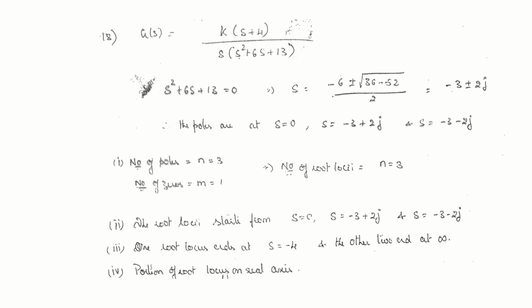Now here I have given a quadratic equation. You are going to get complex open loop poles. So if I do this, minus 3 plus or minus 2j, you will get. So now see here, if I draw the root locus, sigma, j omega,